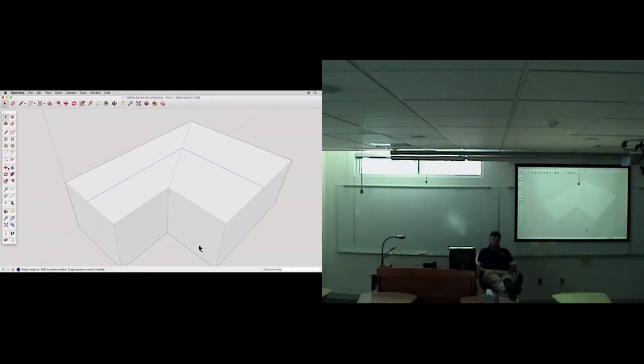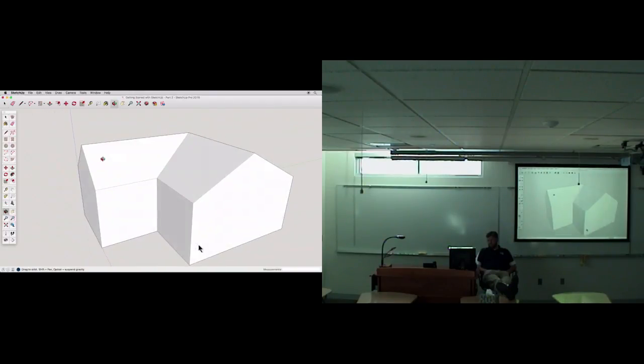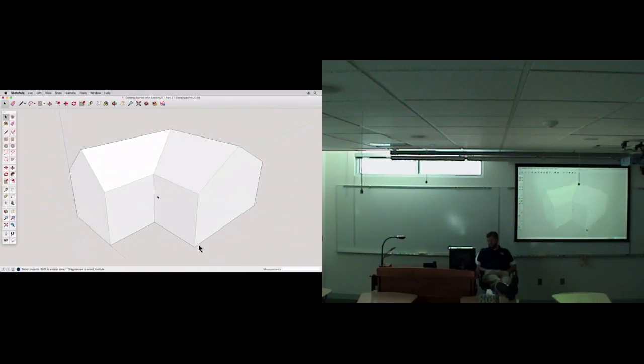Now you can use the Move tool to pull up the roof. When you're happy with your roof, use the Select tool and click away from your model to deselect the ridgeline. Let's explore a new tool, the Offset tool. To see how the Offset tool works, click on the side of our house and pull inwards or away. All the edges of the surface are offset. Click to finish. You can try this on different surfaces to see the results.